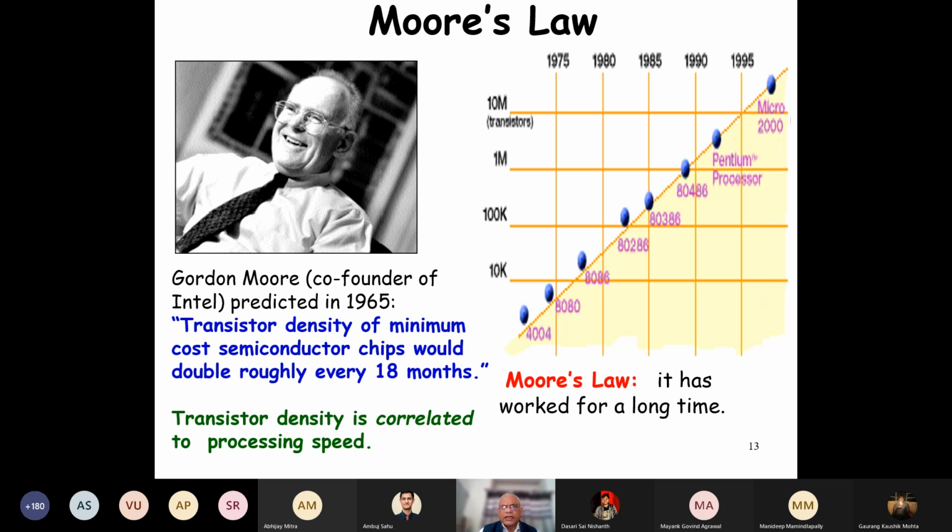See, if it is an adder or a subtractor or a multiplier or whatever, you need some number of gates. If you are given millions of gates, what will you do? So, for example, memory implementations can be changed. Like in a DRAM, one transistor is used and it is comparatively slower than an SRAM, which uses basically 6 transistors. So assuming that whatever you said is correct, what will you do if you are given more transistors? You said 6 transistors are needed or whatever, but then what will you do if still more transistors are given to you?